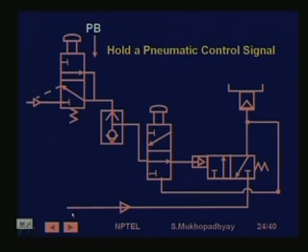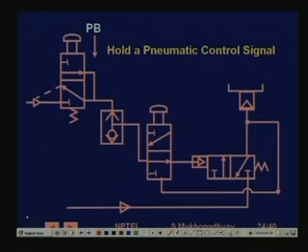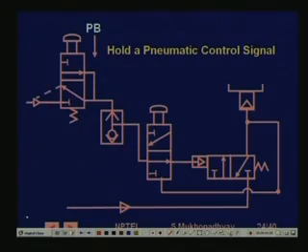Similarly, we show another application. This is a very interesting application where we are realizing something like a pneumatic latch. You know, in digital electronics we have studied about latches. So, we are talking about a latch here. So, then what happens? We actually want to move this cylinder, or maybe it's a big DCV.